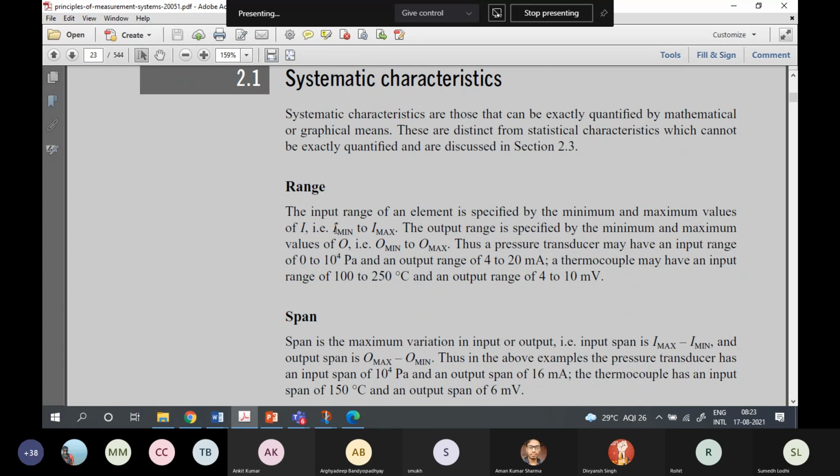So for these reasons, and could be for other reasons also, maybe the sensitivity of the sensor, I mean the characteristic of the sensor changes. For example, the physical mechanisms used to measure temperatures of 1000 degrees centigrade, 2000 degrees centigrade, are totally different from the physical effects that will be deployed to measure, let us say, 5 degrees centigrade, or minus 5 degrees centigrade.